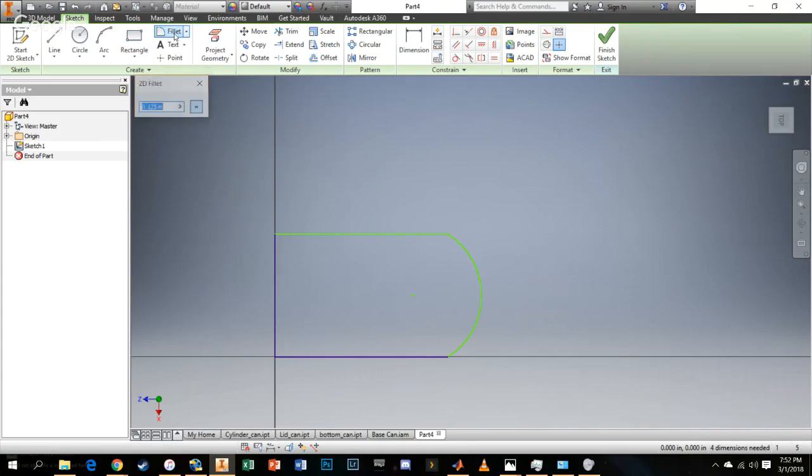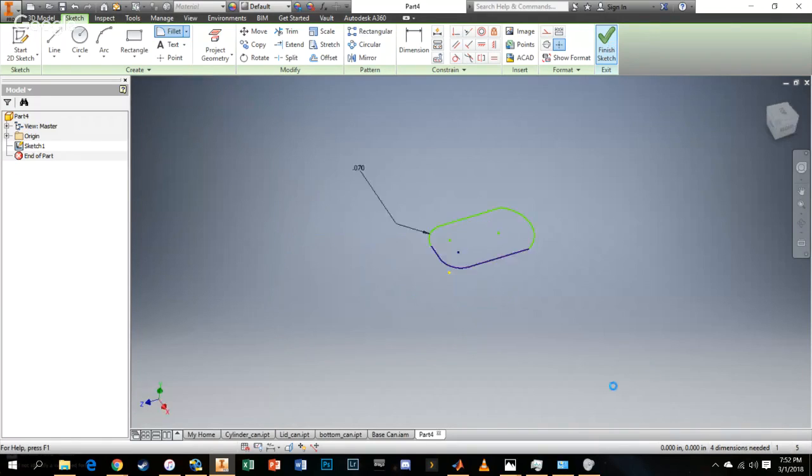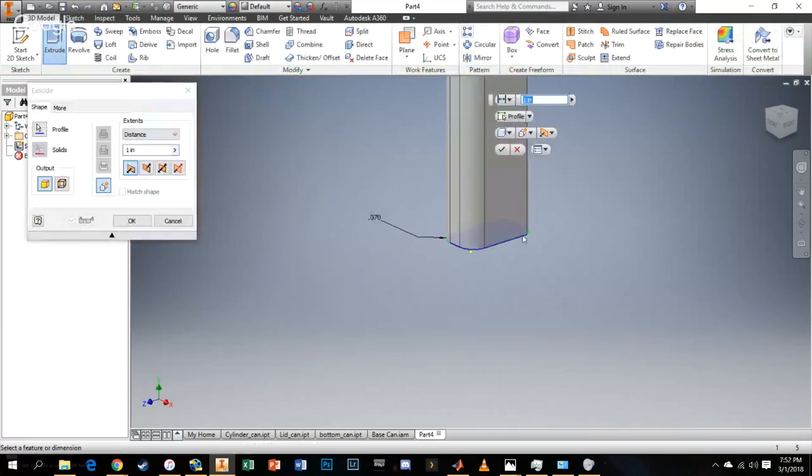And we'll go ahead. The other thing you can do, just to show the different ways, because there's no right way to do anything in CAD, is make a fillet. You put in a radius for a circle, then select these two, and you can see it defines it and rounds it off like so. So there's a pop tab. You can extrude it.